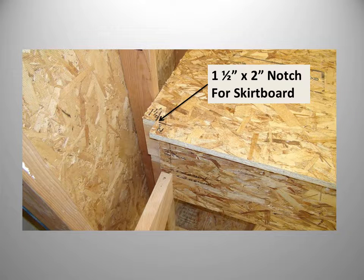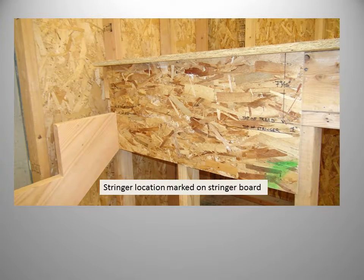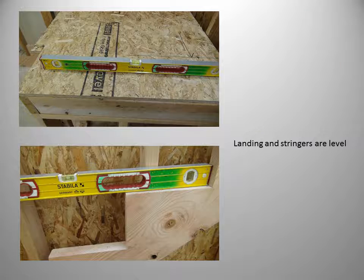Remember that this is to allow for riser materials, tread nosing overhang, and drywall on the opposite wall. We also need to cut a small notch at the subfloor overhang of the lower stringer to allow for the drywall and skirt boards to be installed. Remember to install the 1.5 inch spacer board on the inside of any stringer that is flanked by a wall. This is our space for drywall and the skirt board. Refer to the flooring material concepts lesson for how to locate the top of your stringer. Be sure to double check your stringers to ensure that they are level.